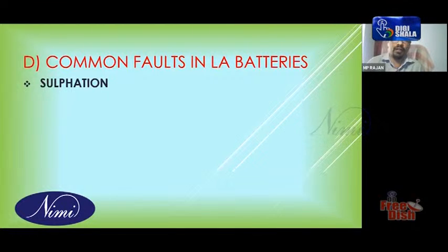It is called sulfation. Once it becomes a very solid piece, concrete-type sulfate, you cannot bring the plate back to PbO2 or Pb. So reversion is not possible. Permanently, जैसे आपने concrete में पानी डाल के concrete बना रहे हैं, after that if you keep it for a long time, not touching, it will become a solid concrete piece. आप उसके बाद उसको कुछ नहीं कर सकते. You cannot make any shape. That is the same thing happening in the battery. This is called permanent sulfation.